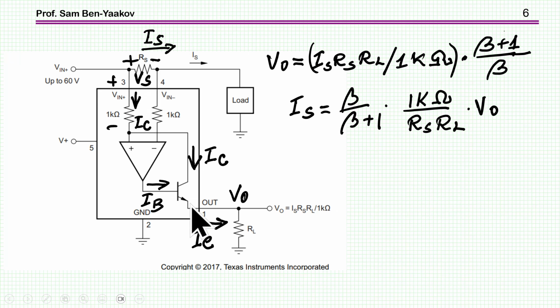The emitter current and the collector current are not equal, they are within alpha. And of course, there is some error here in this measurement if this is a BJT transistor. And the correction is this factor, which is basically alpha. And so this is the same expression as before. And this will then be the value of the sense current as obtained from the output current.